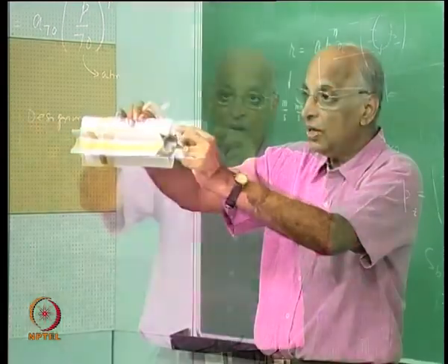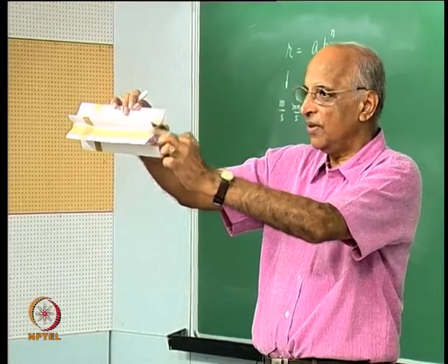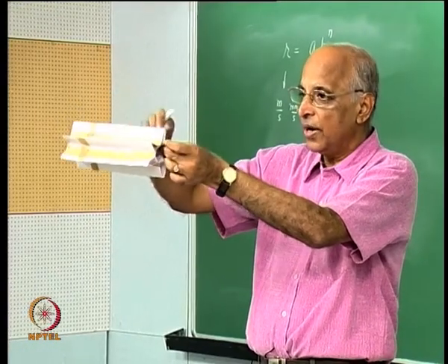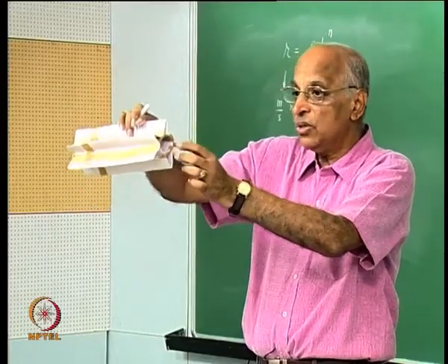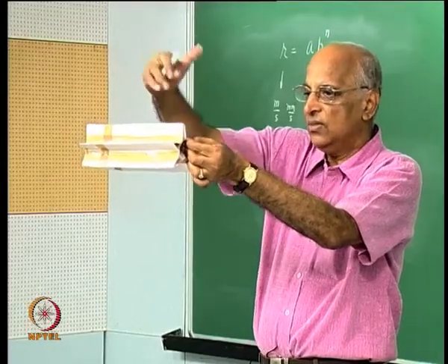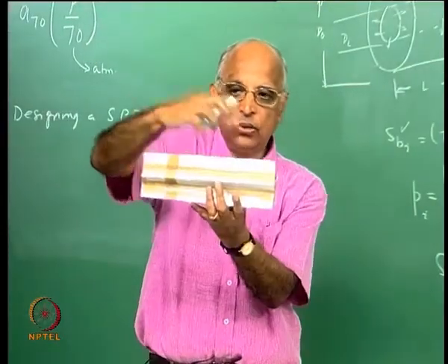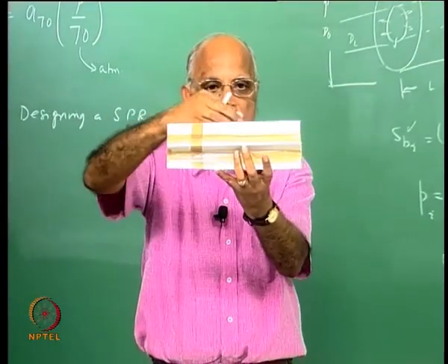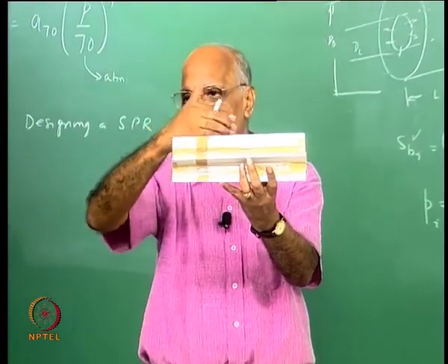Now I find, well, the star, this is something like a five-vertex star, and therefore now I find my surface area has increased enormously. Therefore I must now be able to evaluate how the burning surface will evolve as it continues to burn. In other words, this is my outer diameter, the outer diameter will come over here and the burning surface will evolve along these surfaces, and this is the problem which we must do.